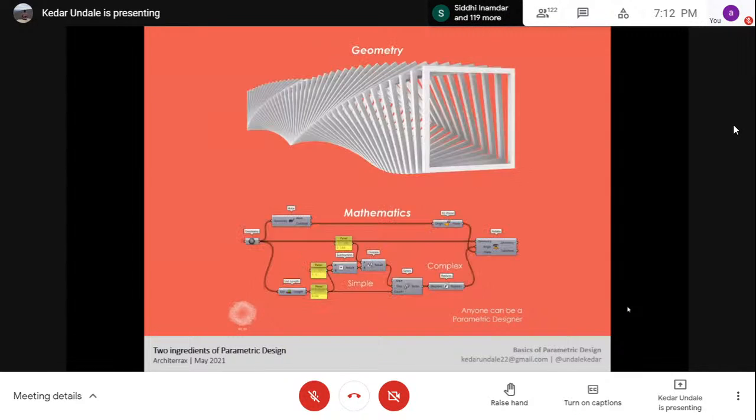And to visually see it, this is how it would look, where this bottom part is a script from Grasshopper. Here also, if you see, it is a simple use of subtraction and division to get this kind of geometric output, which is just rotating of these ribs. And if you see, I have divided by 180 so that I get equal angles. Okay, this radians and all these other things, as of now, I don't want to understand. As of now, what I know is the simplicity of maths and the simplicity of geometry. That is all it takes for me to understand parametric design.